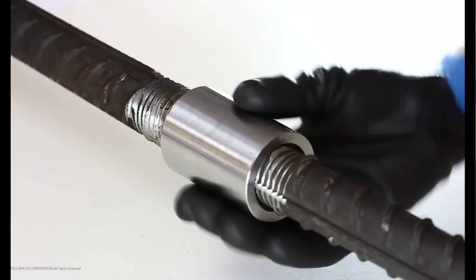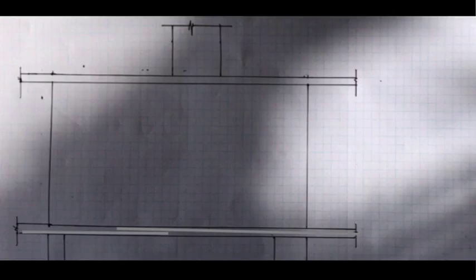Mechanical couplers are technology that allows you to screw in two different rebar from either end, and they are assumed to be fully developed and fully connected to form one long bar. As opposed to the strut and tie method, if you use the deep beam theory, as this is in flexure, you can simply lap the reinforcement at the center of the transfer and it'll be okay because it's in bending and the bars are not going to get pulled out.